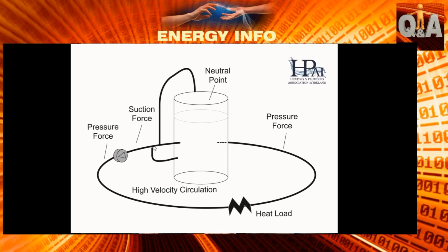In that instance, any air in the system can be lost at the top of the water in the expansion tank or go out through the vent, and the cold feed will fill in any water that's needed as the pressures move within the system. So that's the perfect system for an open vented system.